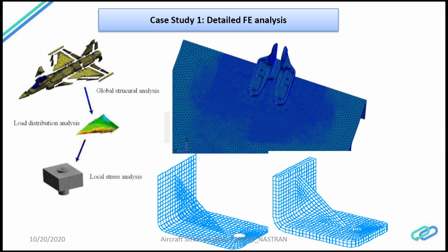So my interest, as I mentioned a few seconds back, is the stress distribution within the panel in the attachment area. That is the reason I have meshed using finer elements and increased the number of elements in the attachment area.